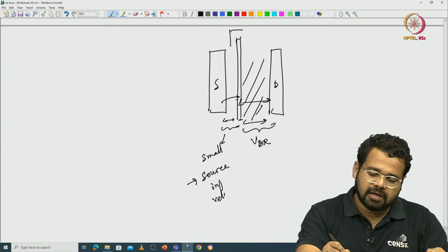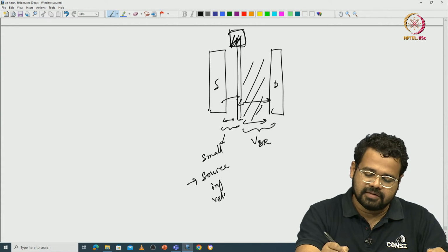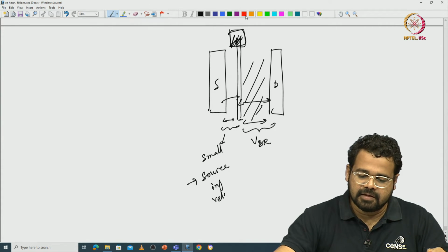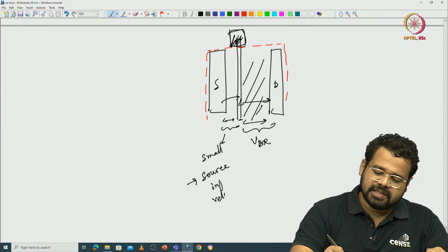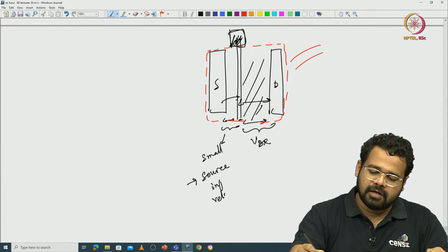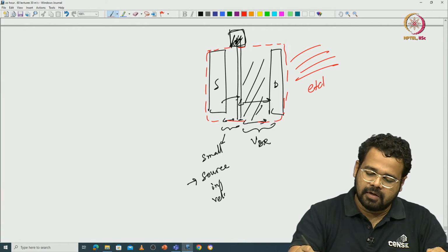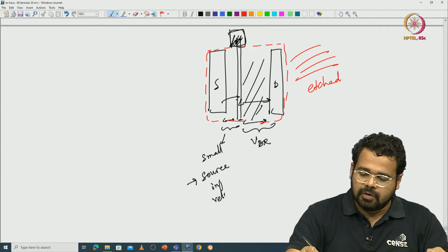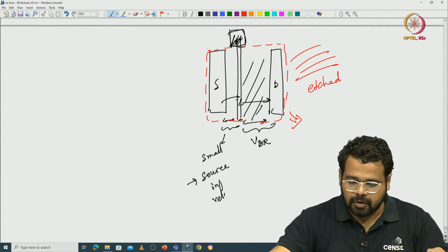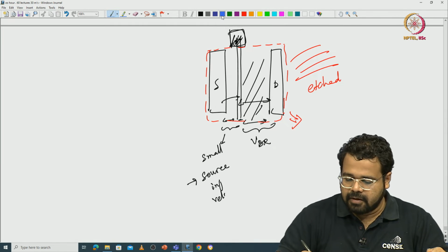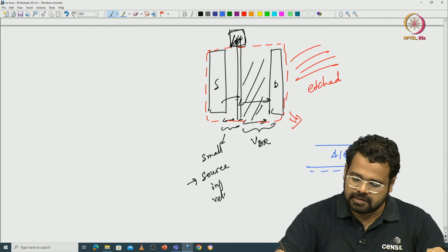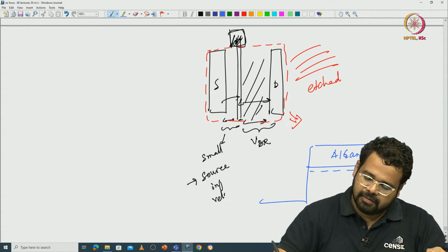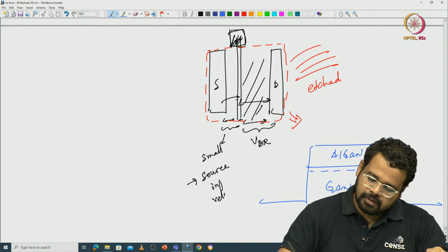And then the gate pad comes here where you are going to probe the device. And of course this entire device has to be isolated. You see this dotted line. This dotted line basically means that everything else here is etched away. The 2D electron gas is etched away, which means if I look at the side view of this, it basically looks like, if this is your AlGaN, and of course aluminum nitride is there, I did not tell you that. If this is your 2D electron gas, then I physically etch the layer, and this is your GaN, and